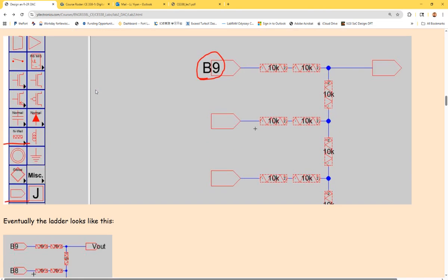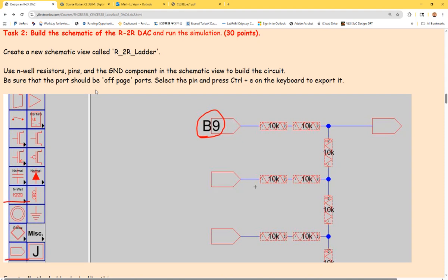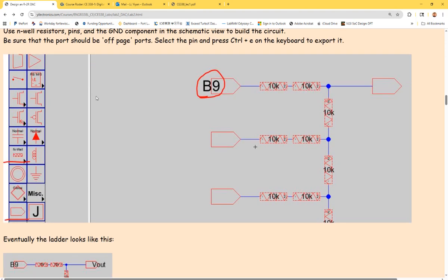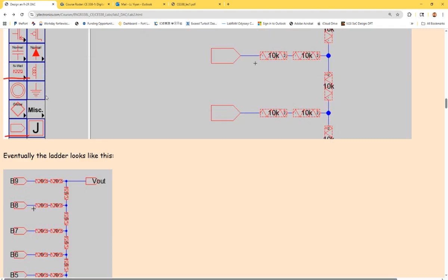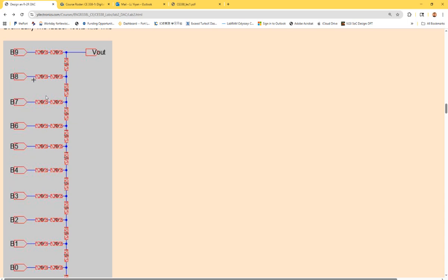And then keep moving. It's asking you to build a DAC by yourself instead of using the DAC being provided. The DAC is way easier, just keep in mind. The DAC is just a resistor string. But ADC could be very complicated. And we'll keep using the ADC from the example, but just to replace the DAC being provided from the example. So you draw the DAC by yourself. It's just a resistor string. We'll cover the calculations on Wednesday.